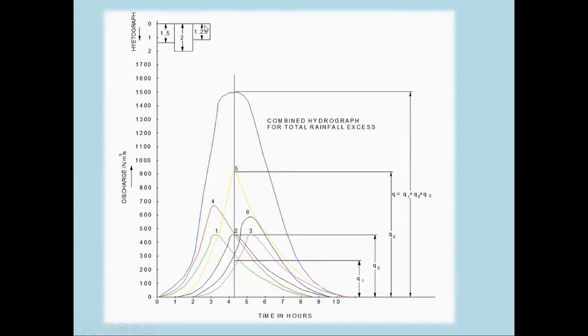Then how to find out the hydrograph for the same sub-basin, because these 3 rainfalls have been explained in this. So what will we do? First, we will draw the unit hydrograph for all these 3 durations. So the first hydrograph I have drawn has been shown in green color. It has started from 0 to 1. It has ended, it is almost 8.5 hours duration.